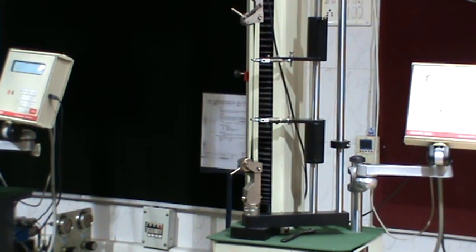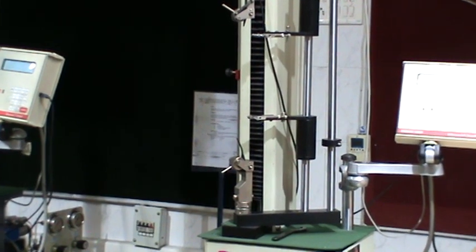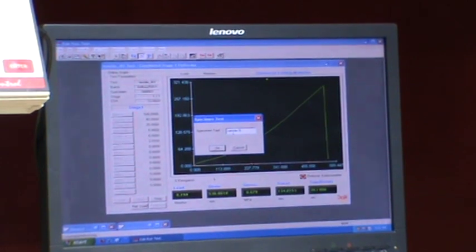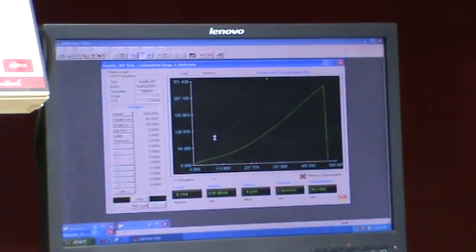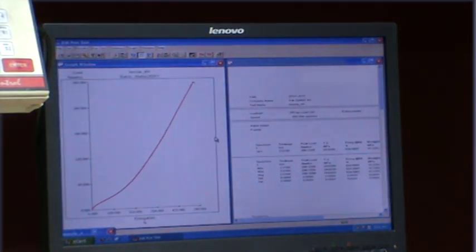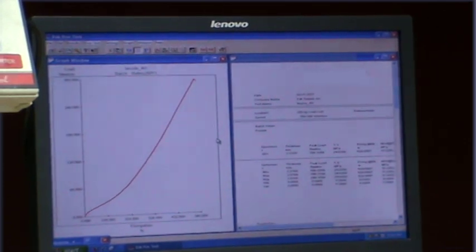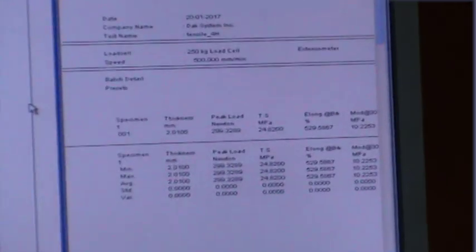Unless the desired application requires the rubber to be stretched during service, then elongation of the rubber is not particularly significant. In rubber lining, for example, the rubber is bonded to steel, therefore the elongation property of the rubber is largely irrelevant. Likewise, for conveyor belting, the fabric or steel reinforcing will determine the ultimate elongation.